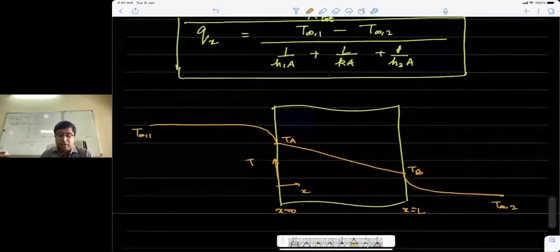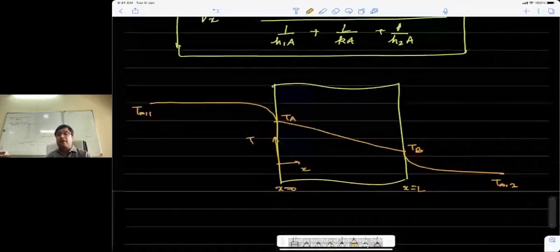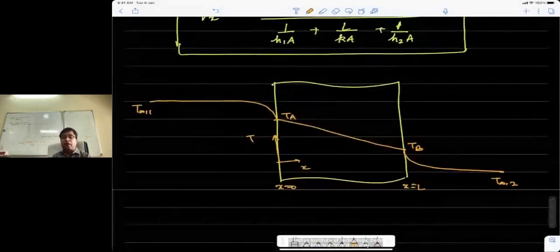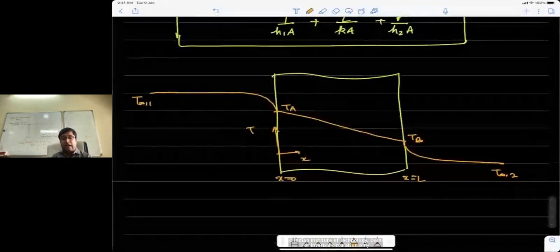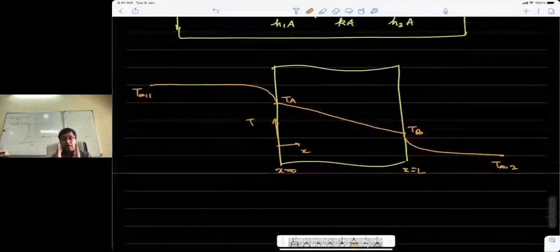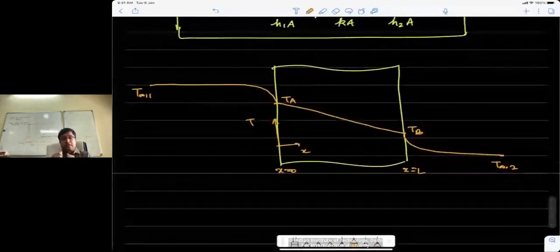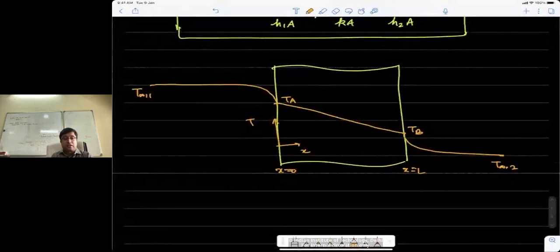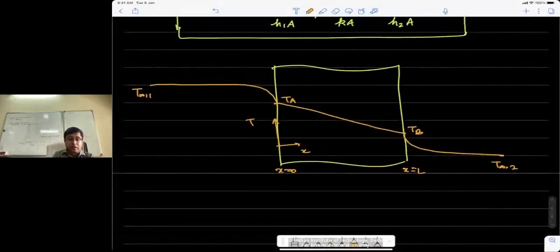No, not on the fluid side, because that is the main difference between a solid and a fluid. In a solid, the molecules are closely packed and in an ordered system, so they will stay where they are. But in a fluid, there's also bulk flow. Remember, this is not just fluid staying there. It would have been constant had the heat transfer only been because of conduction in the fluid. But it is not because of conduction, it is because of bulk flow.